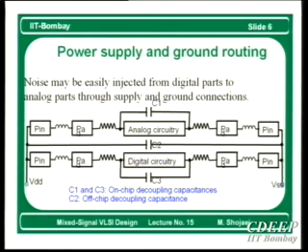Okay, I will explain what those capacitors are. Right now you ignore them. Suppose there is no C1, C2, C3. Now, I have a very high switching current which is drawn from VDD, right? So now I have a high dI/dt. Because of this high dI/dt, the example I mentioned was 100 microamp with 0.1 nanohenry. Now if you consider the inductance is around, say, 1 nanohenry and the current is in the range of tens of milliamps, right? Then this voltage will increase. Therefore, you will have a lot of drop here.